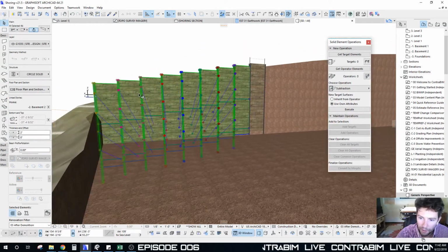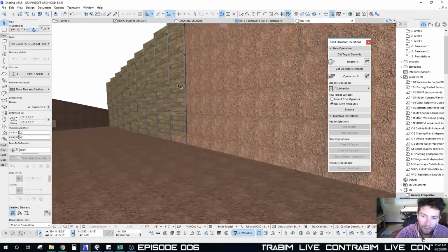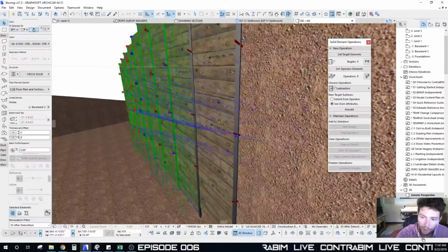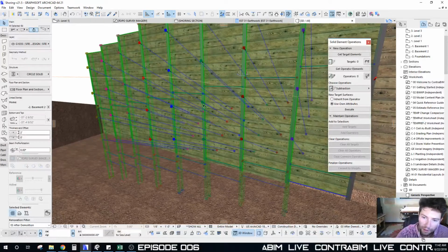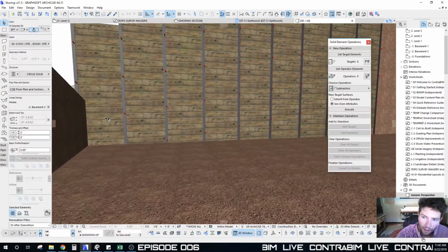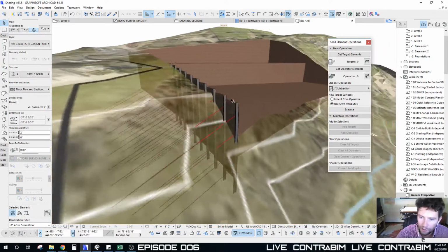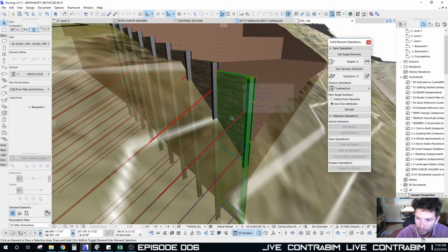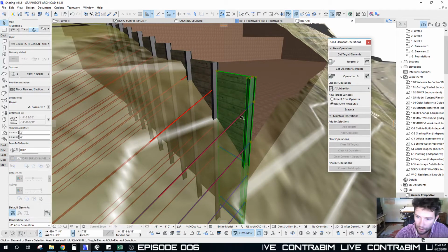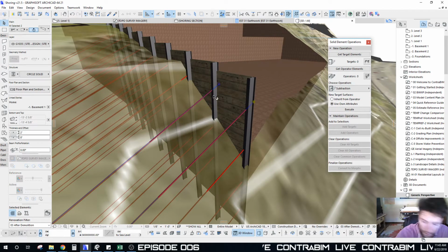And so that brings up the next question: what is the elevation of the tiebacks? Would we actually want them to be sloping in elevation like this? Or would we want them all to be the same level and then just fall off at the top? Because obviously we're not going to need tiebacks right here.